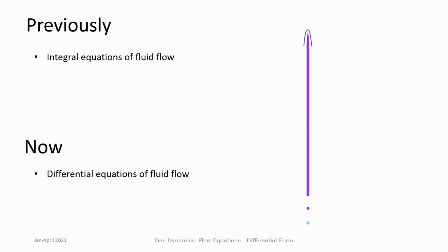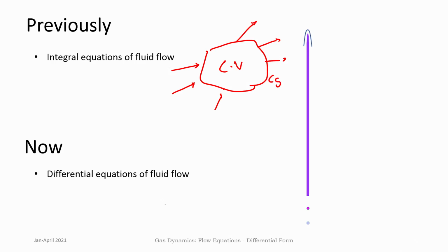In the control volume approach, or the integral forms, we are really looking at analyzing the fluid flow through a certain system which is a control volume, and we look at how changes happen within the control volume due to fluxes which happen across the control surfaces. So, you have control surfaces and control volume, and we write the mass, momentum and energy balance in an integral form. The mass conservation written for this control volume is rho dV, which is the total mass